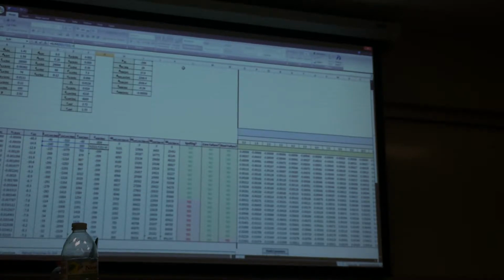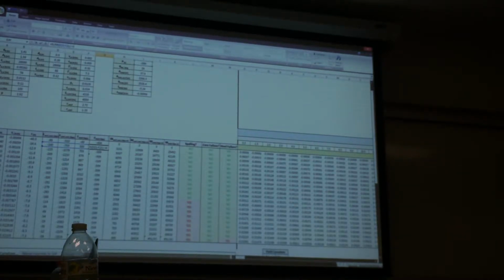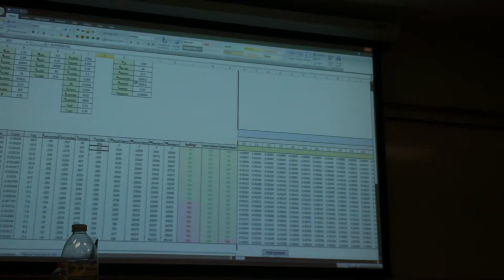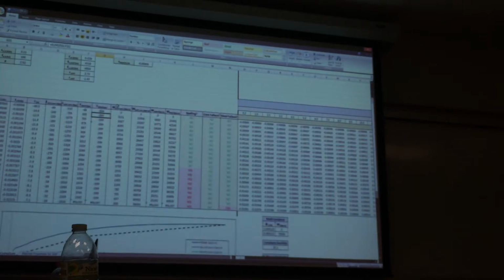The way I wrote on the board initially was you take the sum of those forces, let's say minus your axial load, and then you iterate this to 0. Just rearranging the equation to solve for axial force instead of solving for 0. That's generally the way it's done, because the axial load on the section plays a big deal for moment curvature analysis. We can take some more time to talk about this if you guys like.